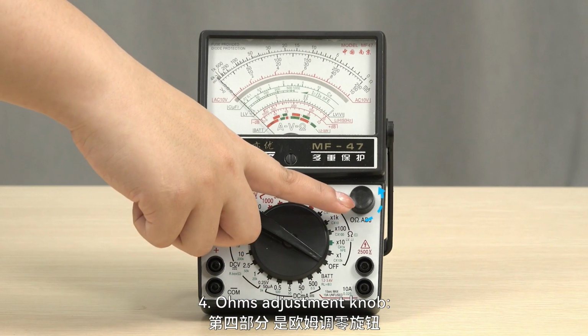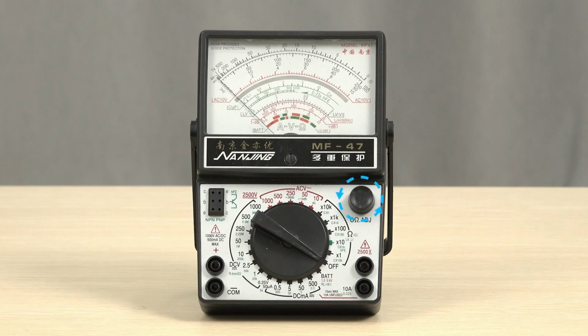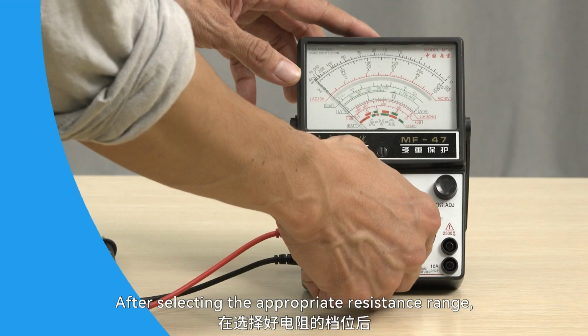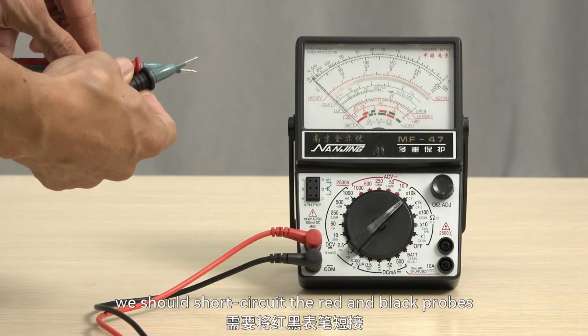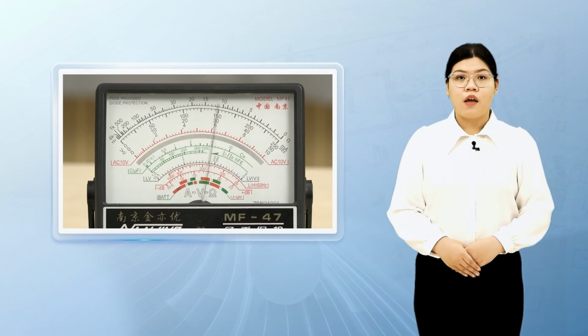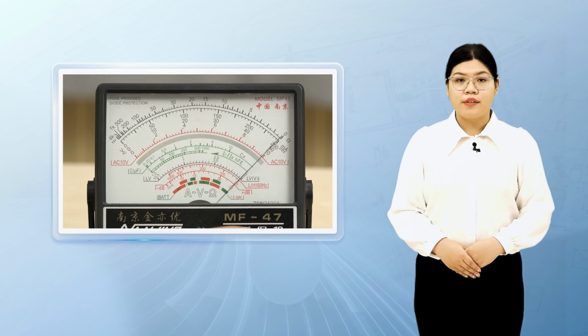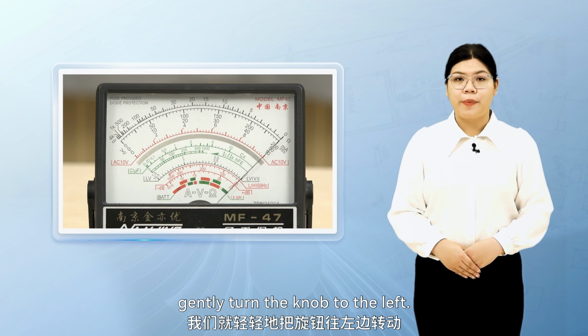4. Ohms adjustment knob. Used to zero the meter when measuring resistance. When measuring resistance, we need to use it. After selecting the appropriate resistance range, we should short-circuit the red and black probes to ensure the pointer stops at the far right zero mark. If it does not, we perform the ohms zero adjustment. If the pointer deflects to the left, gently turn the knob to the right. Conversely, if the pointer deflects to the right, gently turn the knob to the left.